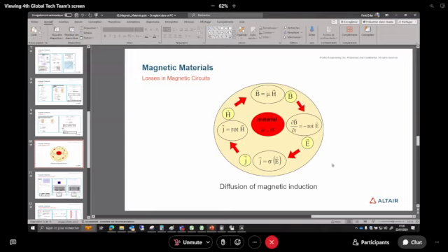Unfortunately, eddy currents are something we don't want to have inside the lamination, inside the magnet. But eddy current, this is something we want to have inside the induction machine. Otherwise, it will not run. Eddy current, this is something we want to have, sorry, in induction heating, for instance, like for a home appliance or some industrial application. So it depends on where we consider eddy current. They can be something we want. They can be something we don't want.